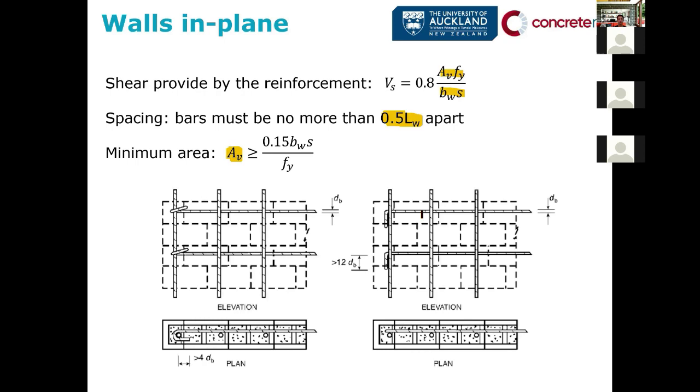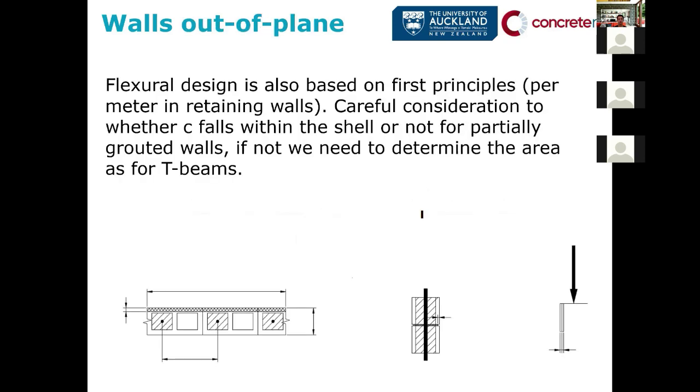And that brings us to out of plane design. So the flexural design is also based on first principles. If we are doing retaining walls, which is one of the most common uses of concrete masonry walls, then we usually do it per meter, because we may have a 20 meter long wall or 10 meter long wall, so it's simpler.